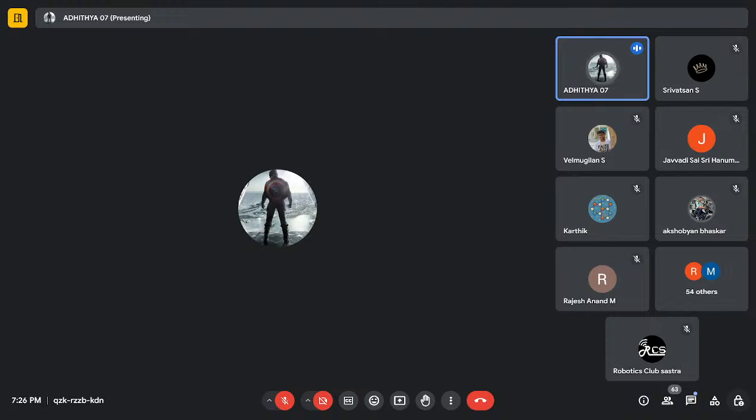In the void setup, we use LCD1.begin. What begin does is set up the LCD display so that it can start to display. Once you give begin, the backlight will be on, the whole display will be empty, and the cursor will be set at the start, which is 0, 0. Just like in computer science, arrays and everything here also start from 0. This part calculates the distance from the time. For LCD print, we give a 500 millisecond delay for simplicity, and LCD1.clear to clear the LCD. This is a very simple circuit we have done here.